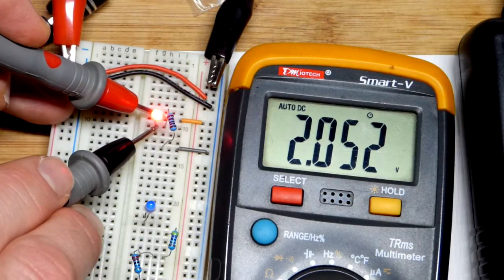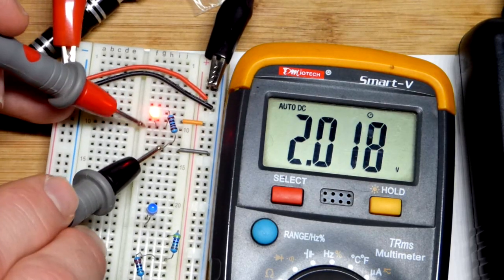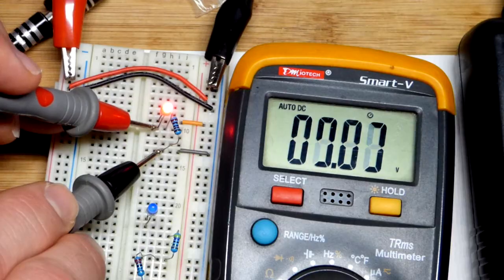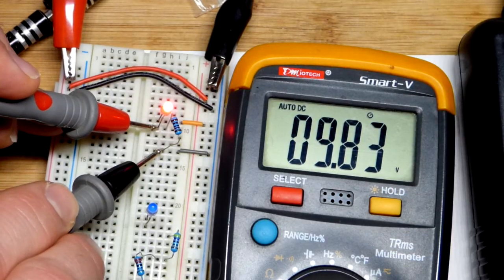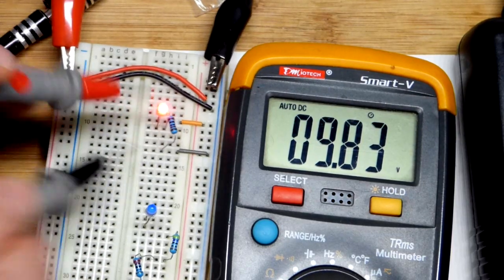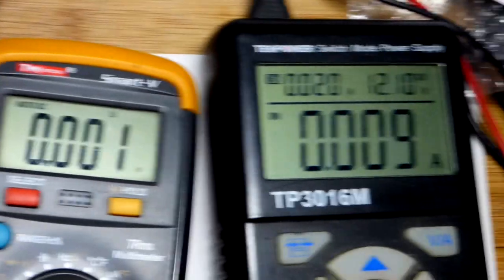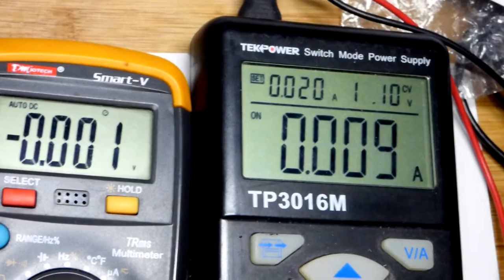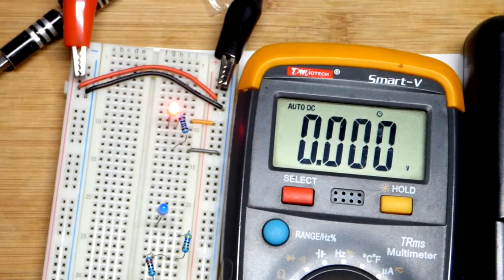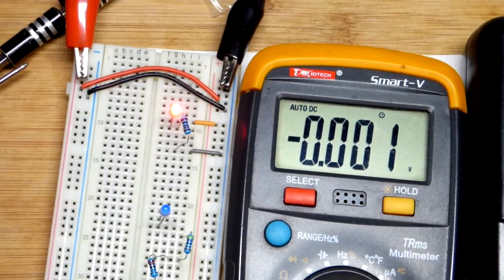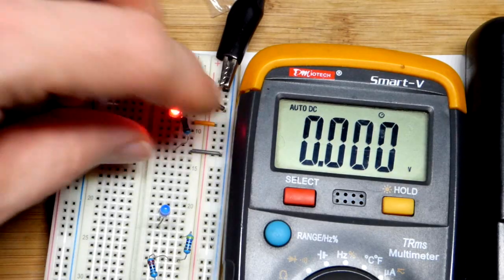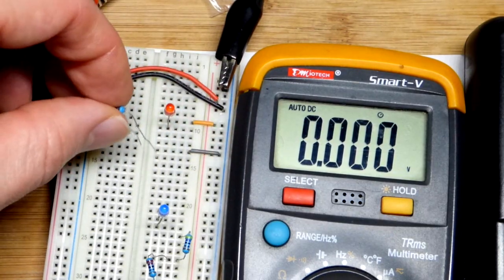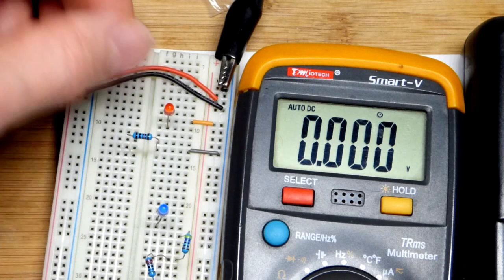You'll get almost completely all of the voltage across the load, but here we're falling short. Again, we're working with 12 volts, but the LED still drops 2 volts, no matter what. So we got 10 volts across the 1000 ohm resistor, which gives us about 10 milliamps of current. There you can see 12 volts, and it's showing a little bit less. So, these are not perfect numbers. If that's like 9.9 milliamps of current, it will still say 9 milliamps, the way that power supply is. It doesn't round up.